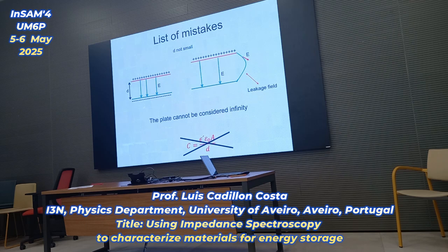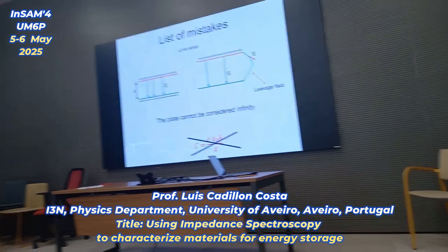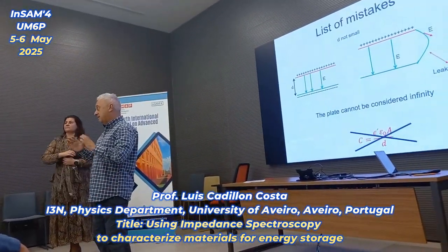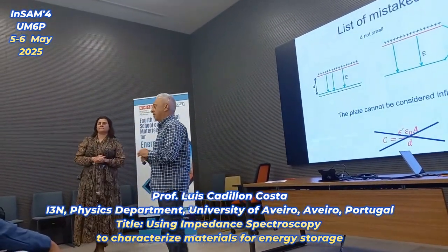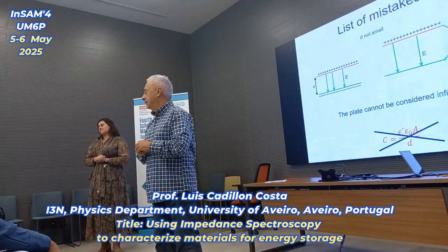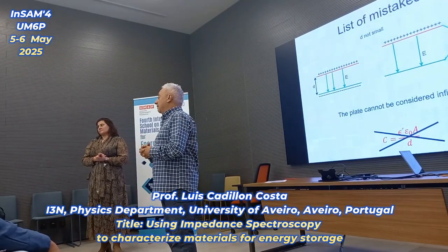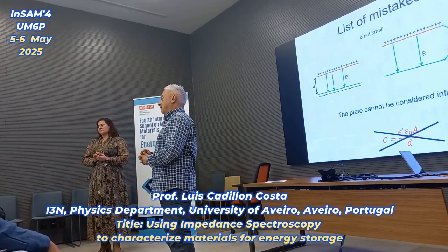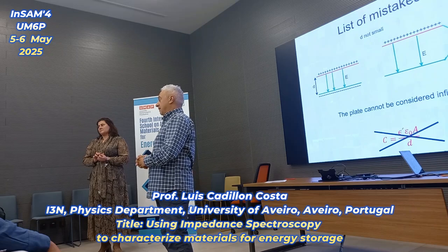We must have a compromise. You must increase epsilon prime, but not increase epsilon double prime too much. And this is the big physical problem. There's something for energy harvesting. It's important to try to increase the dielectric constant so that there's more charge across the electrodes. Yes, yes.